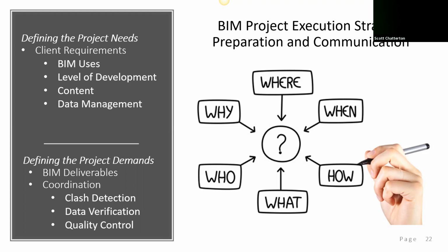So data includes your room schedules, your room name and numbers, your equipment list, equipment type, your doors, your windows, materials that you use. All of that is data that can be extracted out, and really that's the I in BIM. It's the building information that's contained within the model that we can utilize. So we need really good information in so we can extract really good information out.